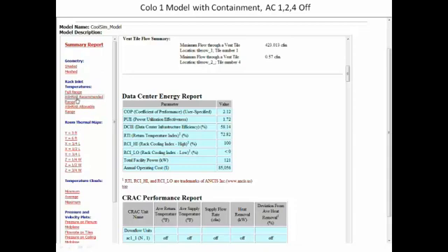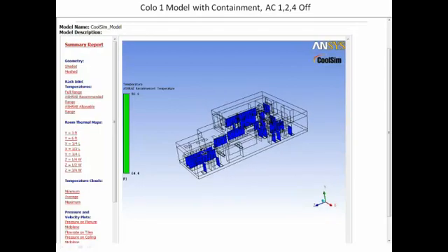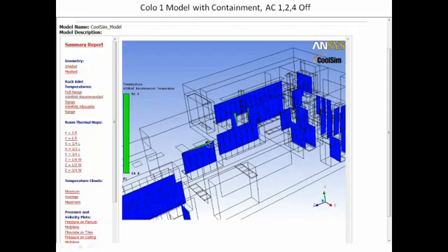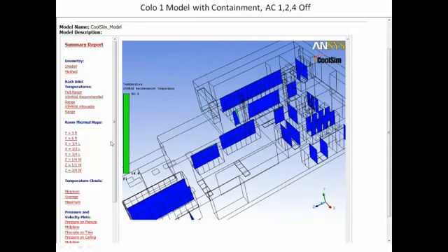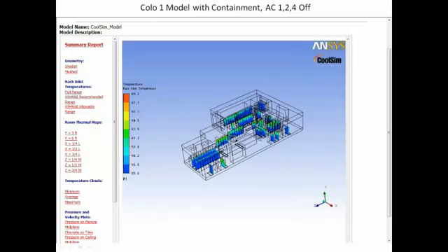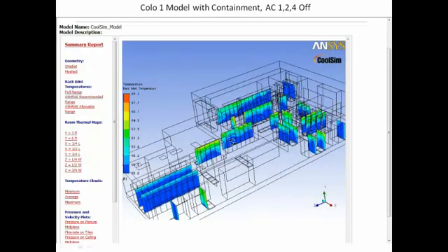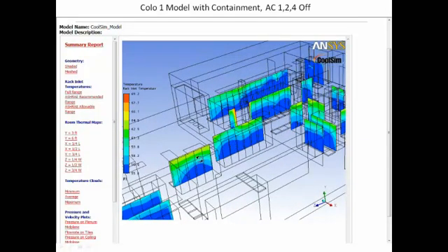Now, let's go take a look at our rack inlets. We'll look first at the ASHRAE recommended range, and we see we're still too cold here, Liz. The whole thing's too cold, but we see some indications that things are getting some improvement. Some improvement, yes. If we look at the full range of inlet temperatures, you'll see here that the contours are starting to develop because I've reduced my airflow. And it's always a little hotter at the top, right?